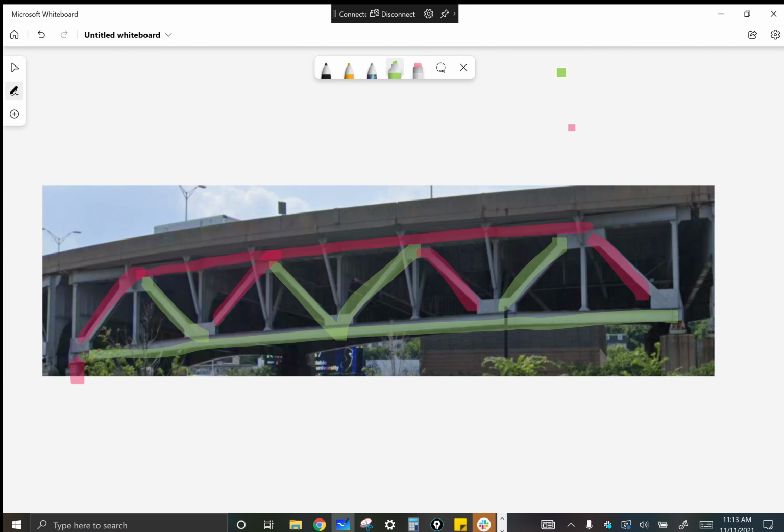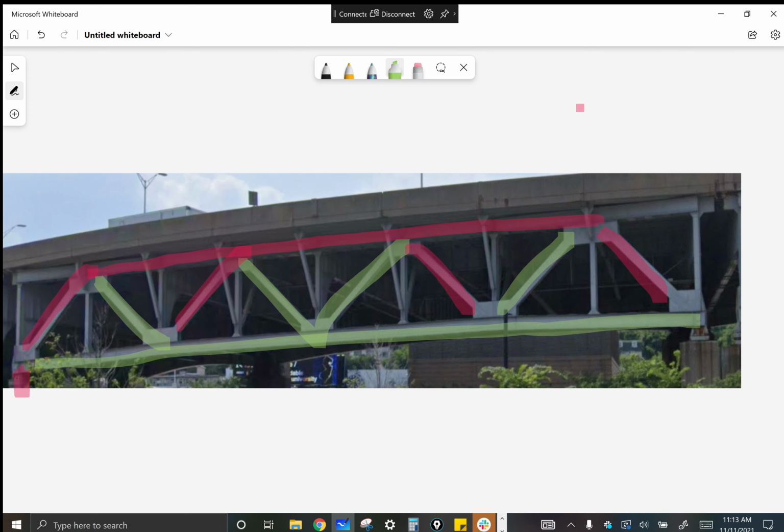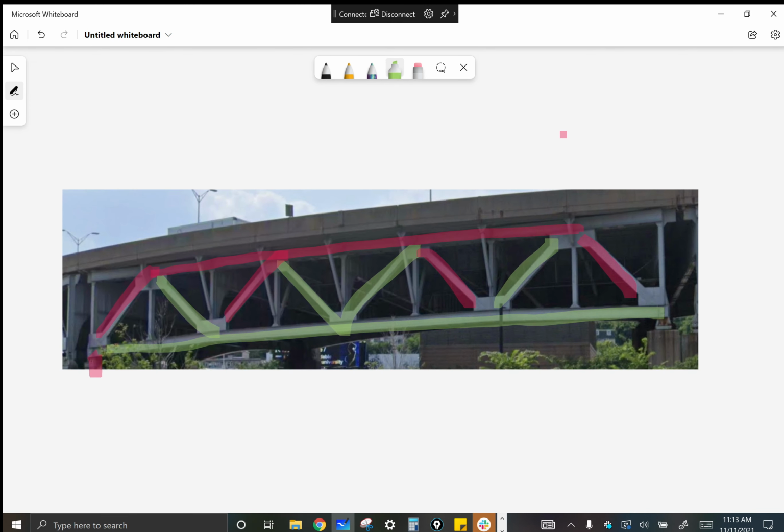But what else do we have just looking at this basic thing? And then I'll get to the really simple one we've always been talking about. So we're positing that this is a simple planar truss, but there's so much other stuff going on here. Like, for example, we have these giant joints, and in simple planar truss theory, we've always said that those have no volume. So that's clearly a case where we're talking about what we're doing in the actual truss project, where we have to have a physical joint, and we have to consider how it's going to affect the actual truss.